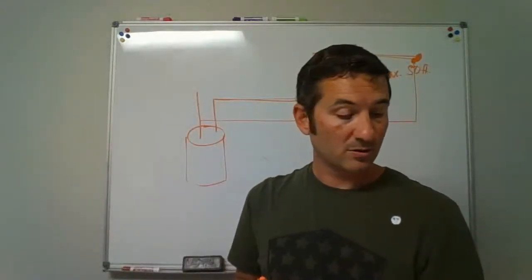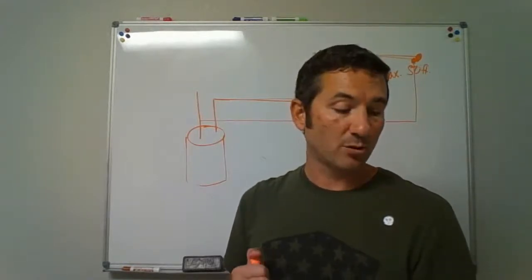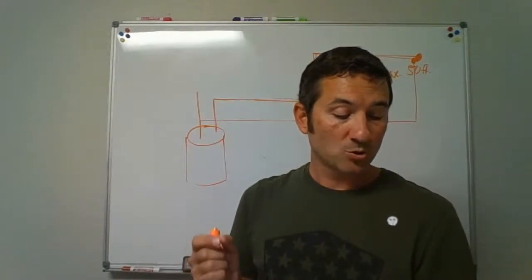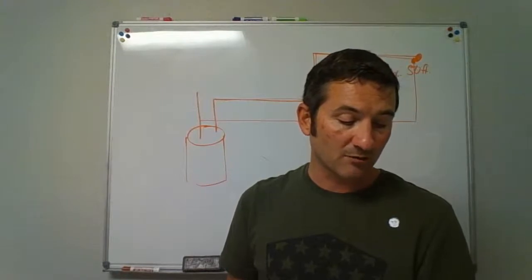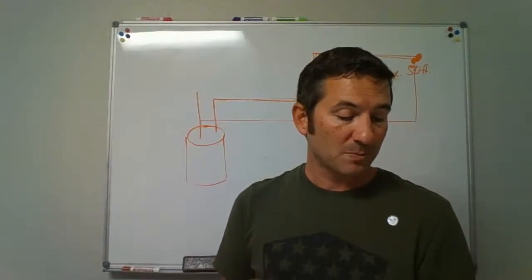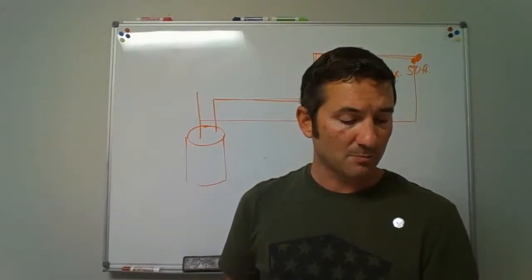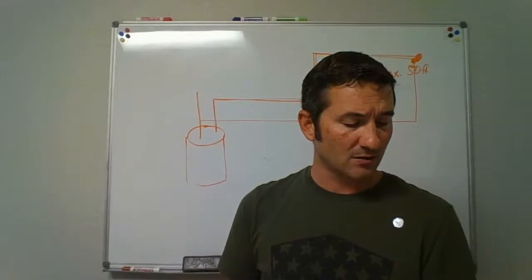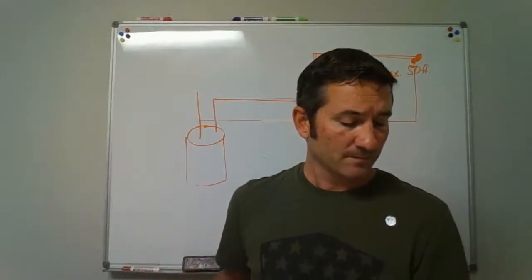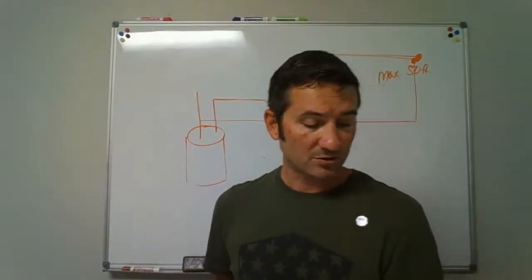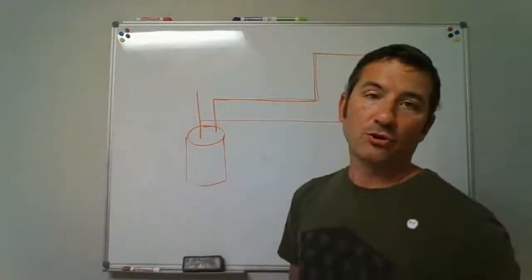Then it deals a little bit with thermal expansion controls, 607.3, where a storage water heater is supplied with cold water that passes through a check valve, pressure reducing valve, or backflow preventer. A thermal expansion tank shall be connected to the water heater cold water supply pipe at a point that is downstream of all check valves, pressure reducing valves, and backflow preventers. The thermal expansion tank shall be sized in accordance with the manufacturer's instructions and so forth. Read that. So that's what we've been putting in, thermal expansion tanks.